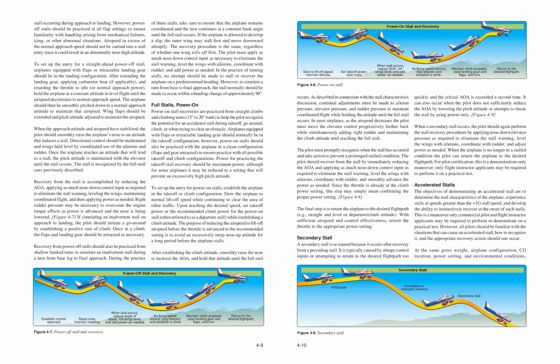In the practice of turning stalls, no attempt should be made to stall or recover the airplane on a predetermined heading. However, to simulate a turn from base to final approach, the stall normally should be made to occur within a heading change of approximately 90 degrees.